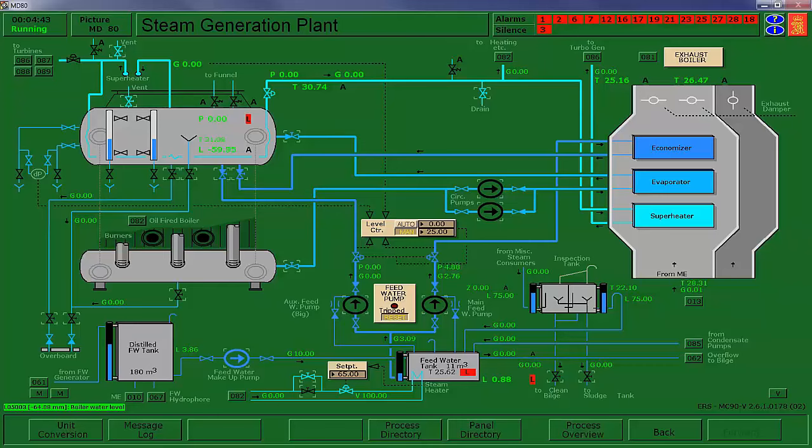Now, once that's done, we can go ahead and put the level controller in auto, and we'll leave the set point at mid-drum with the feed pump on. We're not producing any steam right now, right? And if I leave this on, there's always a small amount of leakage past that feed water regulating valve. So a small amount of water would be going into that drum, and it would be drifting the level up.